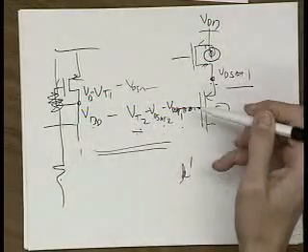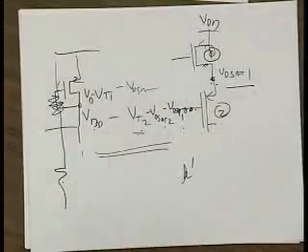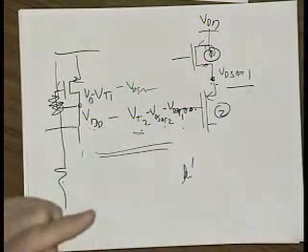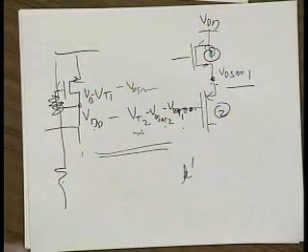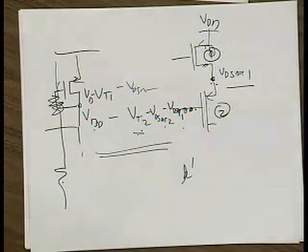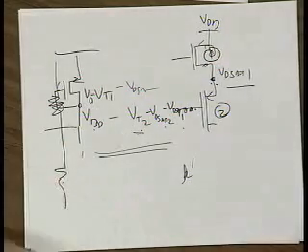You call that replica biasing: making a replica of your circuit and pulling the voltages off that replica, where instead of having inputs, you now have just DC values. And you get DC voltages that replicate what's going on in your circuit. They're not a function of the input, and you can keep DC bias points correct. That's a more general approach to this biasing problem. We haven't talked about that too much here, though we've kind of implicitly done it. But that's something you would do in 240.